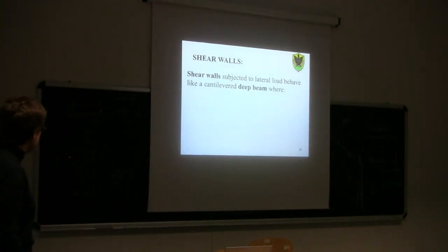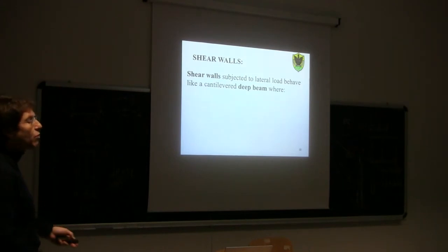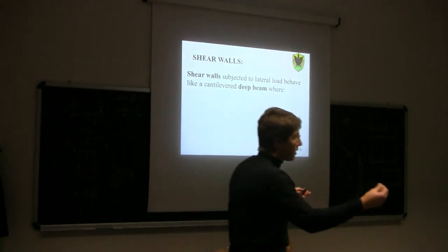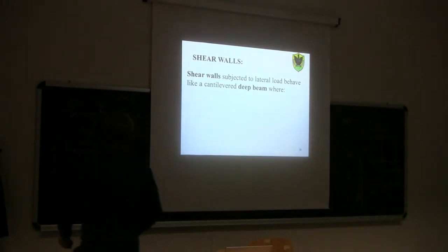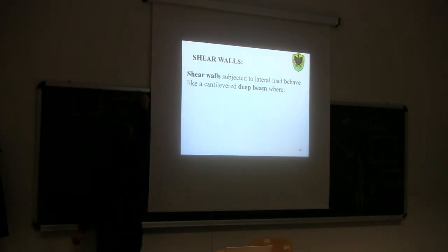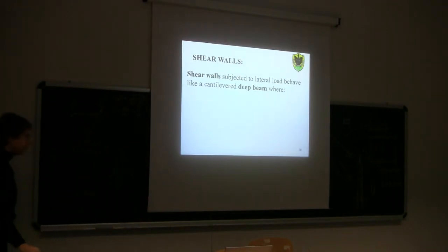Meaning that we discovered that in the end, for the lateral resistance, who is going to contribute to the resistance to lateral forces are the two outer studs. One stud in compression and the other stud in tension. The tension and compression can be calculated with very simple equilibrium. So in the end, M divided by D, which means F times H divided by D. Okay? So this one, C equal to T, is also equal to F times H divided by D. Equilibrium, compression and tension. Okay?